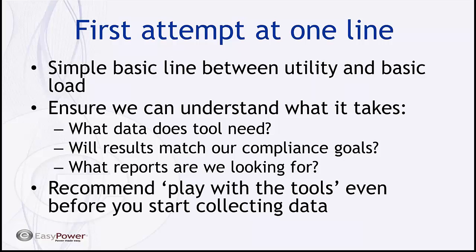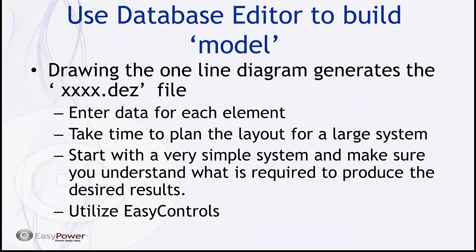I recommend that you play with the tools a little bit, especially if you're going to be doing the data collection, because you'll have a better understanding of what the tool requires, and of how the arc flash results will ultimately mean a better and safer system and a better understanding of your system. The database editor is used to build the model.